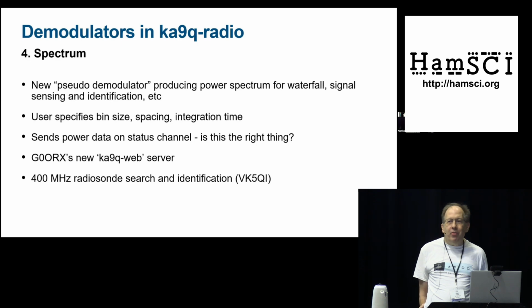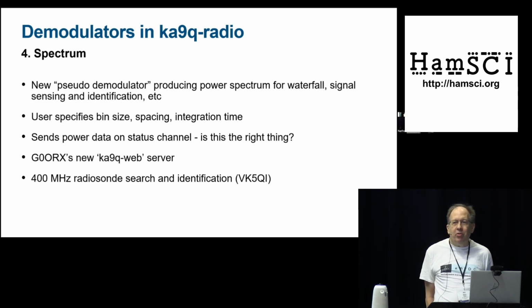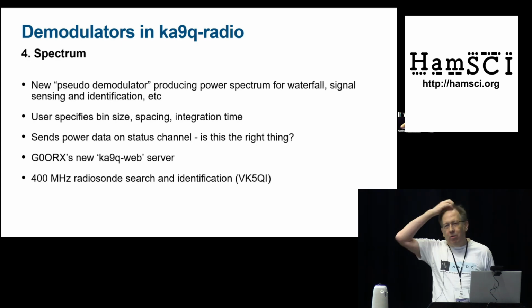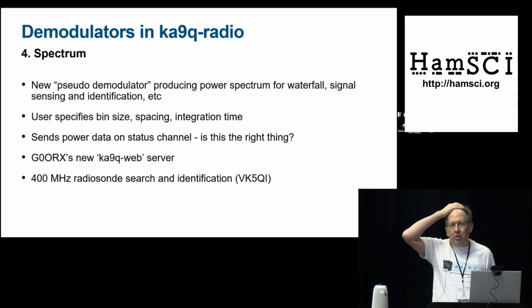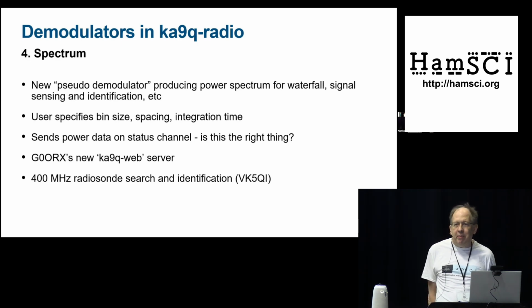And very often they float. They're designed to float around the altitude where rockets go through max Q, the point of maximum aerodynamic pressure, where they're most susceptible to wind shear. And I've seen them float up there for hours, just floating on past LA and Orange County until the batteries run out. And so if you have receivers that can only receive one at a time, you may miss the one that you really want. So having a multi-channel capability is really handy.